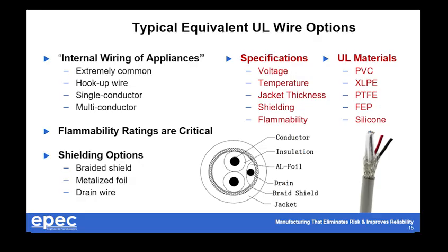PVC remains one of our most common and the lowest price option for many of our customers. However, PVC does have some limits. It's not the best in terms of high temperature, ultra high voltage, or flexibility. However, it's wildly effective in most of the low complexity and hookup wire applications that we see. Cross-linked polyethylene, Teflon and its derivatives, and even silicone are very common materials for us.